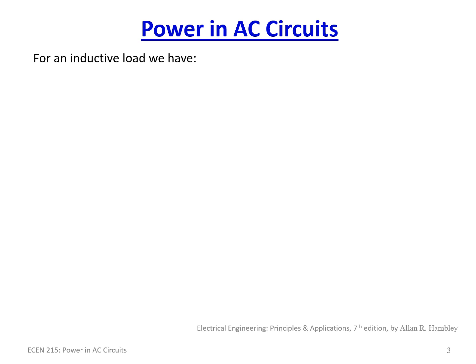For an inductive load, now this is a purely inductive load, and we're going to cover in a few moments what we call an RLC circuit, which is truly a complex circuit with all sorts of different inductance and capacitors and resistors. But what we looked at a moment ago was purely resistive. This is purely inductive. So here we have an impedance that is just omega L with a phase shift of 90 degrees. And here we have, current is V over Z.